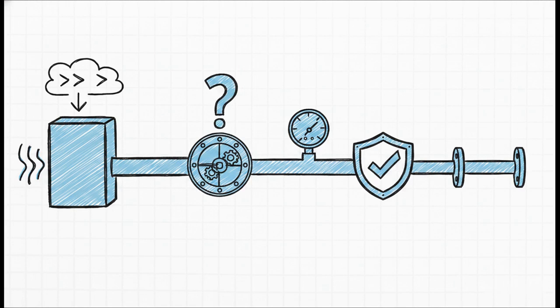Question 6. If the answer is no, you must keep the higher, heavier piping class extended downstream until independent protection exists. Build this rigorous habit. Internalize this logic. You will never make the classic spec break too early mistake, and you'll finally understand why your lead engineer meticulously marks up your drawing reviews the way they do.